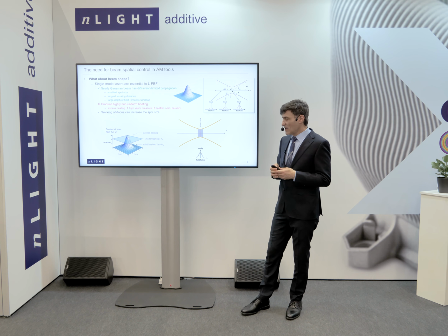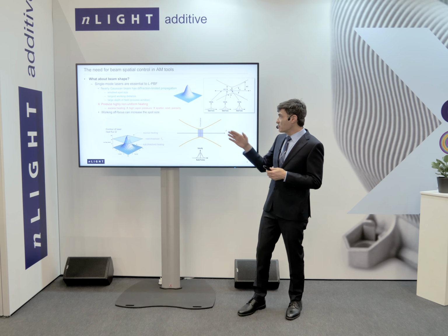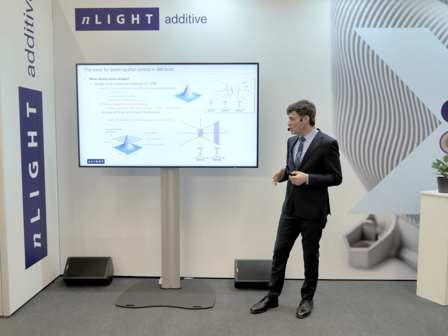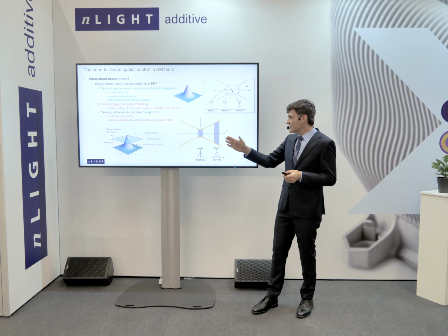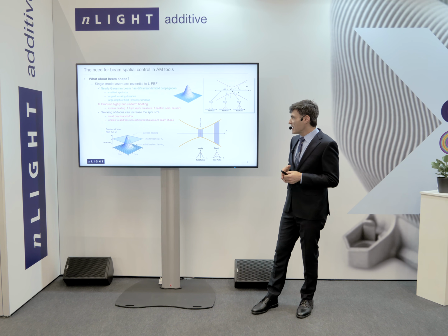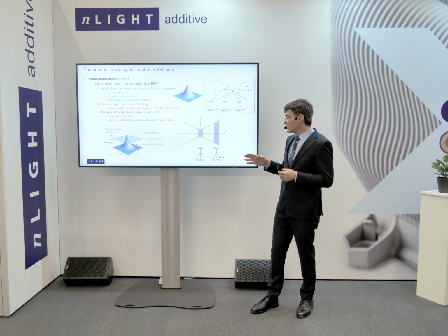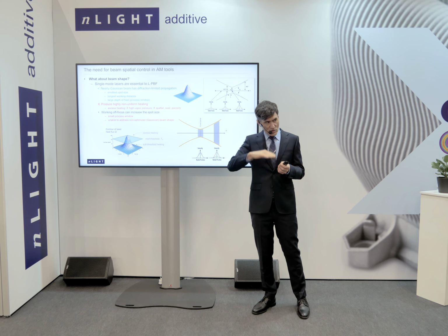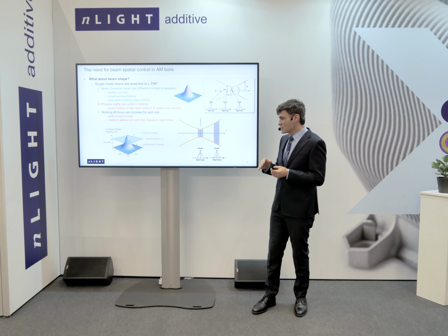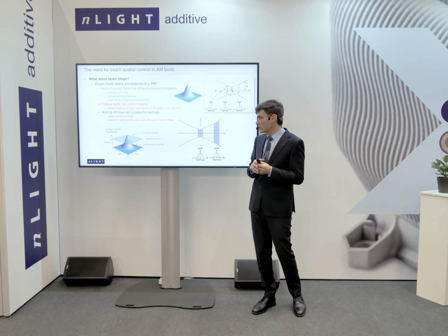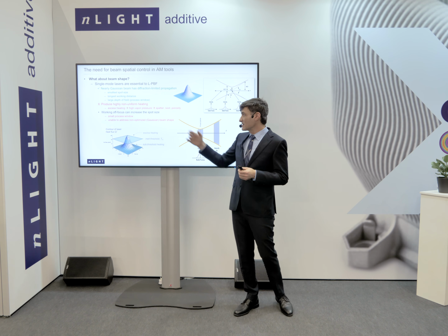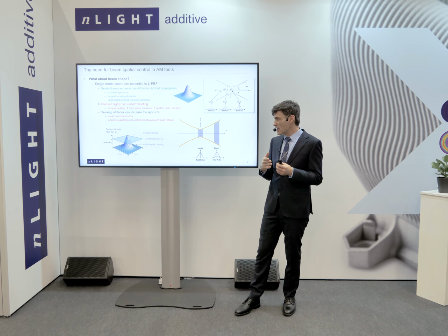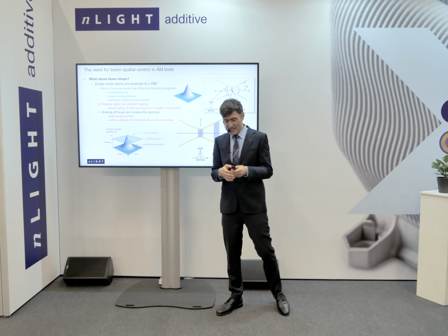Current tools will attempt to address the problem of size by working off focus. That is, moving the workpiece away from the focal plane. That makes the beam bigger, but it reduces your process window because now the spot size is changing drastically with position, and so you get a very small process window. Also, this doesn't address the non-optimized Gaussian beam shape. The larger beam still has the Gaussian shape and thus still has the excess heating problem.